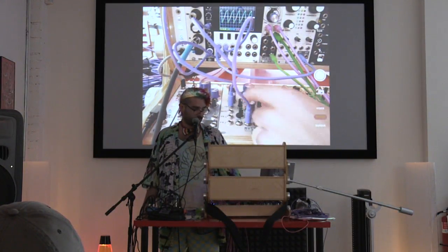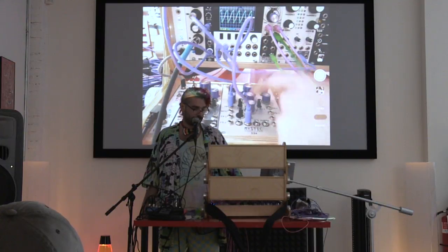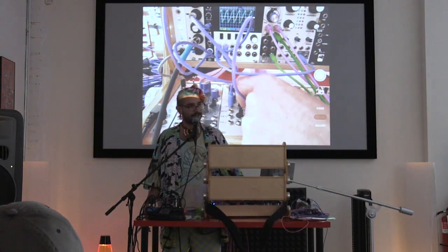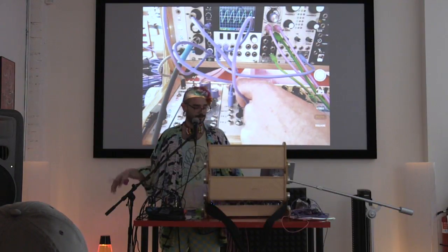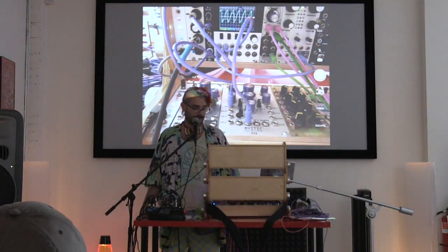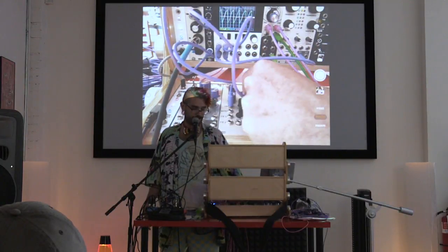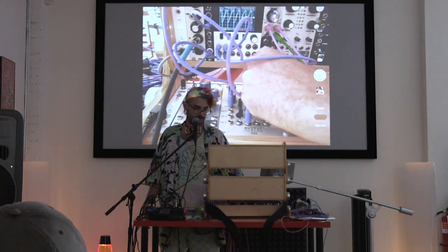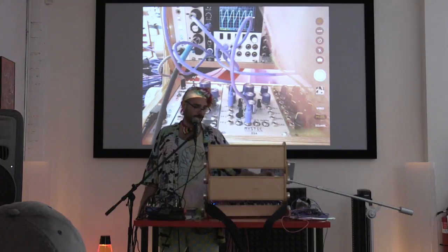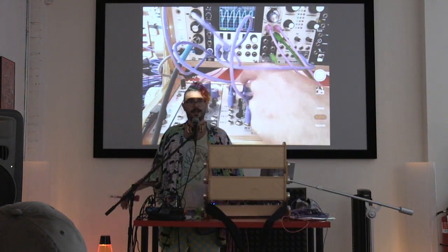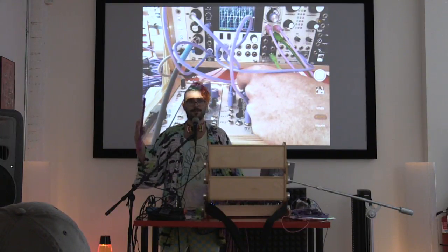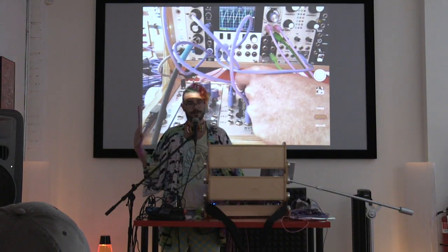Now, the feedback goes through a bipolar VCA, so negative feedback is actually like a more subtle kind of soft effect than your positive feedback, which is going to get loud. And you can hear, like with a low-pass filter that's resonating, it's really emphasizing that cutoff frequency.